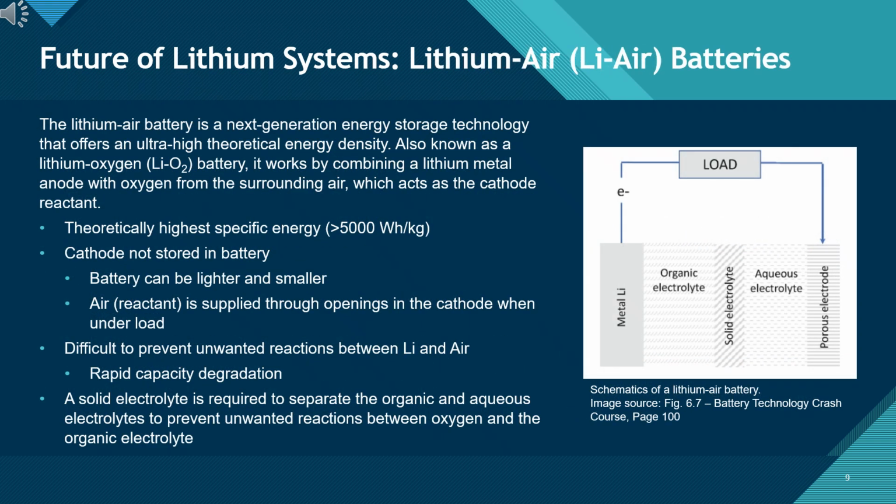Future of lithium systems. Lithium-air, Li-air batteries. Now we move on to lithium-air batteries, often called Li-O2 batteries. These represent one of the most ambitious next-generation energy storage concepts, offering the highest theoretical specific energy, over 5,000 Wh/kg, which is even greater than that of Li-S systems. Unlike conventional cells, the cathode reactant, oxygen, isn't stored inside the battery. Instead, air is drawn in through openings during discharge, making the system lighter and more compact.